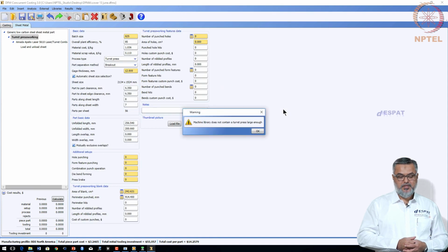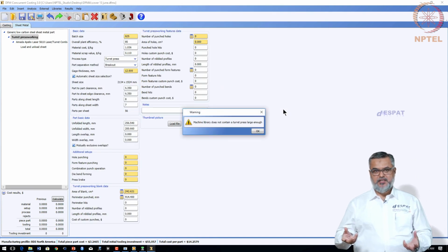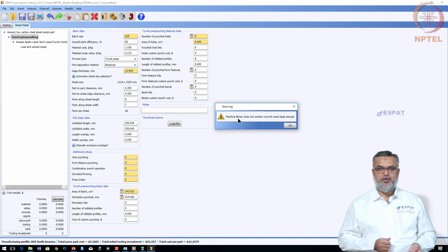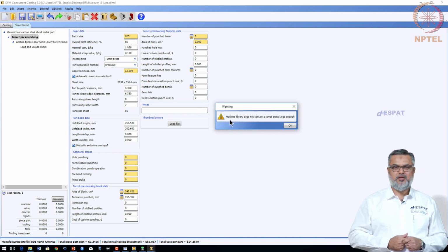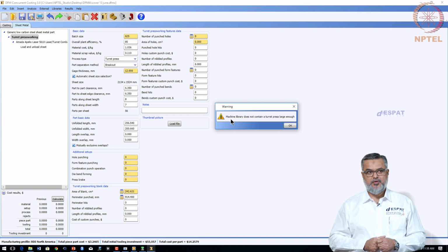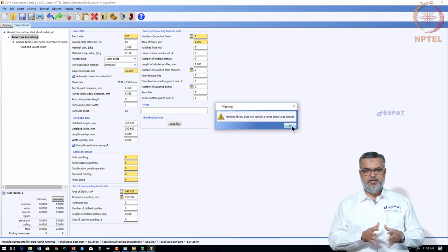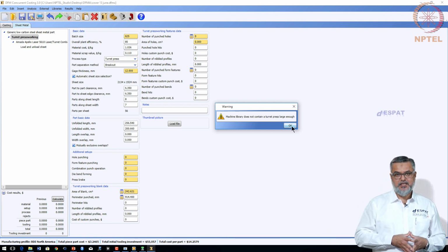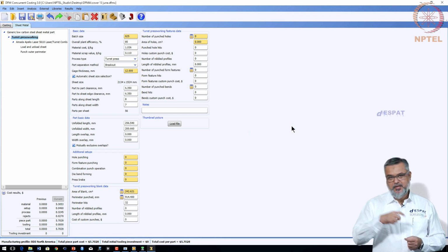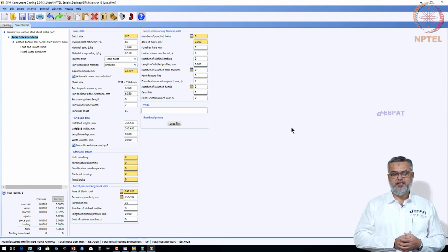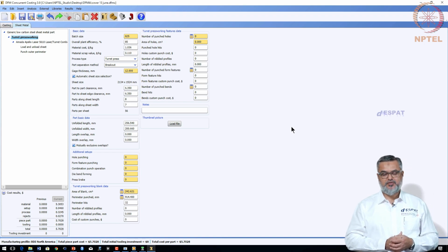And you will see that I will switch the process from the current casting to sheet metal, and here I have another problem: the dimension that we have taken, 12 mm, is unlikely to be practical, because we do not have a material library that can actually stamp a 12 mm sheet. What I am trying to say is this tool facilitates as a knowledge base to help the designer get a rapid feedback of his design intent by saying what is possible and not possible with the criteria that he has selected for manufacturing his part.